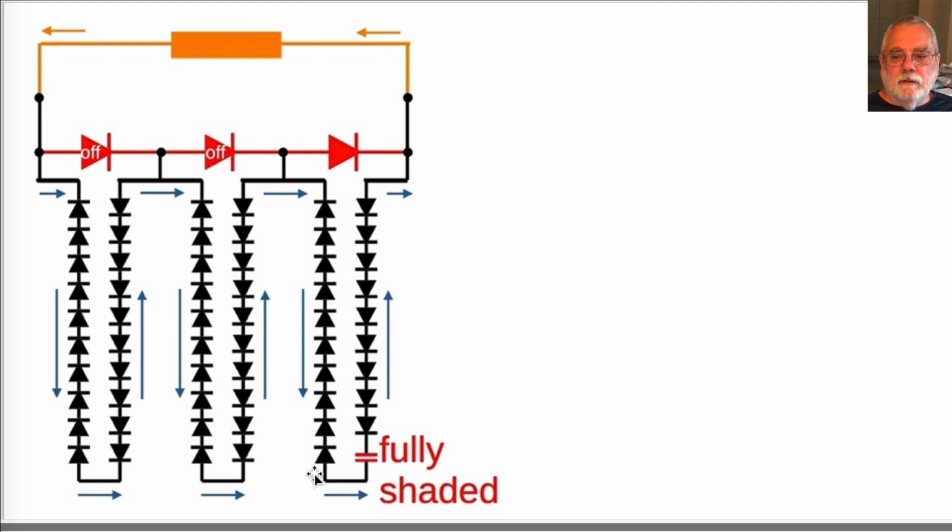Series current from the fully illuminated solar cells continues to flow, but now that current is charging the capacitor in the reverse bias direction. The reverse bias continues to grow until the bypass diode turns on. If there were no bypass diode, the reverse bias would grow until either reverse breakdown voltage is reached or all of the illuminated solar cells reach their open circuit voltage and current ceases.